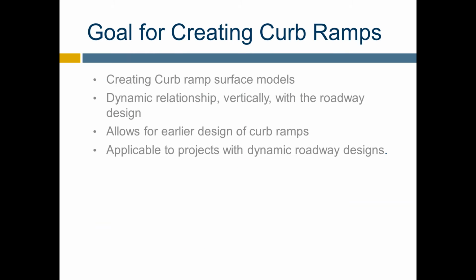So the goal for creating curb ramps is to create curb ramp surface models. Today we will be discussing curb ramps using a dynamic relationship, and this is vertical. If your roadway design changes horizontally, you'll have to go through this workflow again because this is a vertical dynamic relationship.